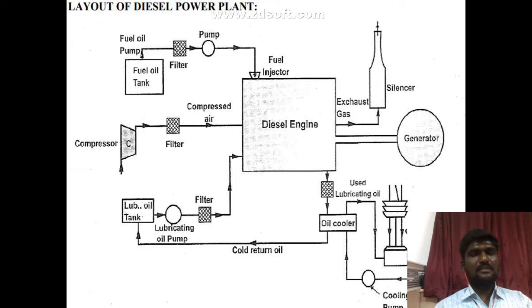Diesel power plants are mainly suitable for small and medium outputs. We do not generally use them for large plant outputs, only for small and medium outputs, right? Diesel electric power plants ranging from 2 megawatt to 50 megawatt capacity are used as central stations, right? Diesel power plants are commonly used where fuel prices and reliability favor them, and supply demands are low, in favor of oil and coal, where fuel supply is limited in the area. They are mainly used as peak load plants, right?